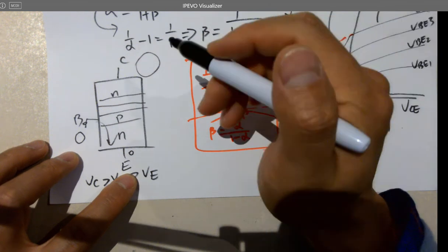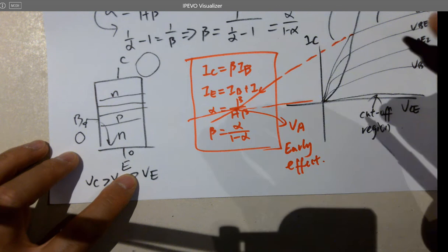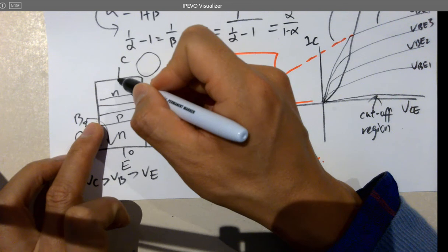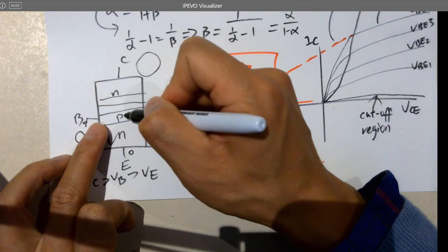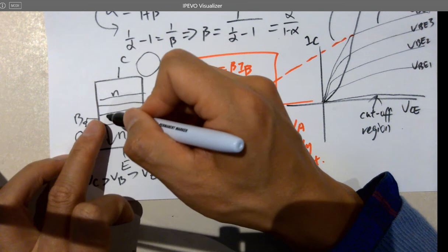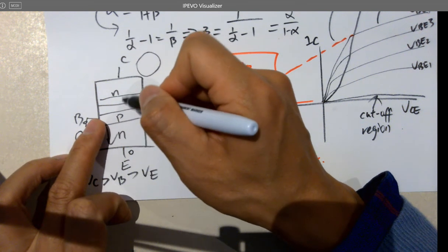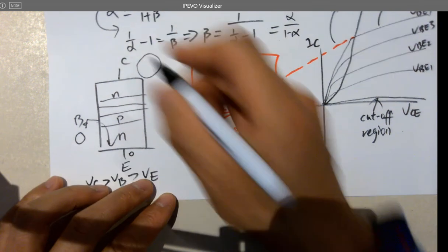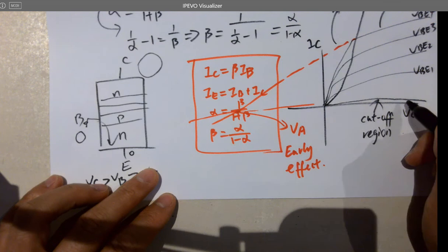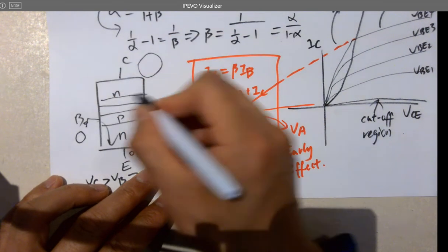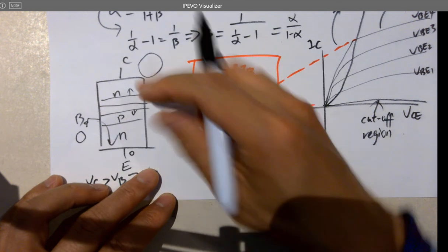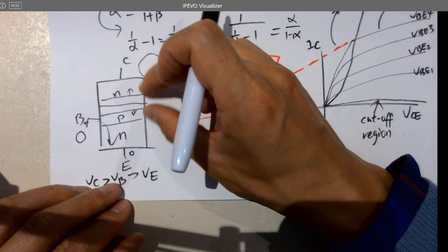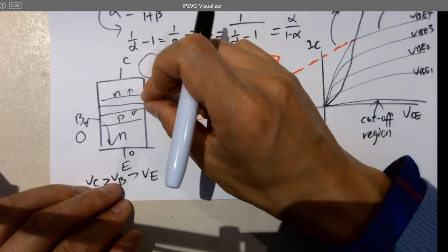But now, before we just understand that the charges will tunnel through all these layers of depletion regions and make that happen, if you are only looking at this PN junction here, it's NP, right? And the voltage at N is larger than the voltage at P. So how is this being biased? Reverse biased. Okay, it's being reverse biased. So when I increase VC, what's happening for this PN junction here? For the depletion region, is it getting larger or smaller if I increase the reverse biasing voltage? Is this depletion region getting wider or smaller? How to remember that? Remember from last time I told you?